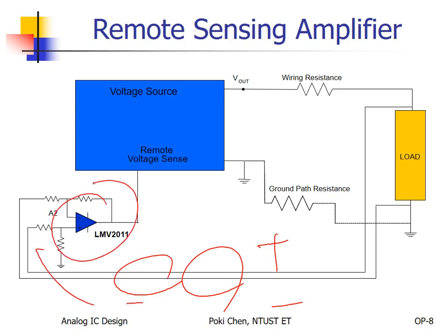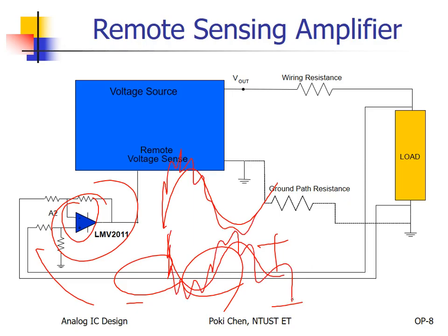After going back to the control center, because an op-amp is supposed to amplify the difference of the input signals instead of the common value, if those two signals are jammed with exactly the same noise or interference, then after taking the difference, the same interference will be subtracted out from each other, right?